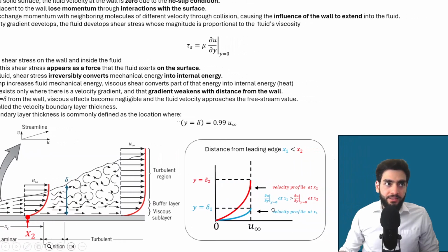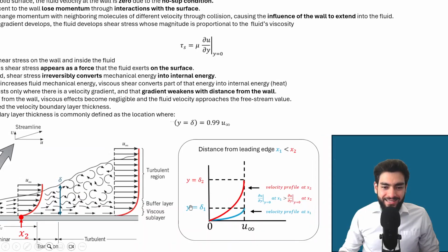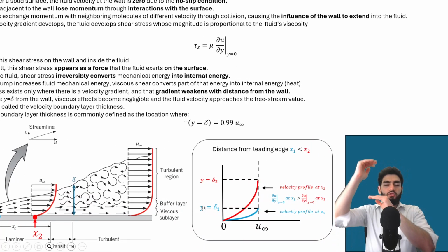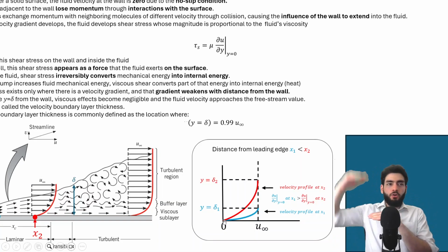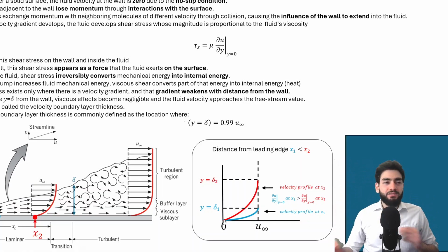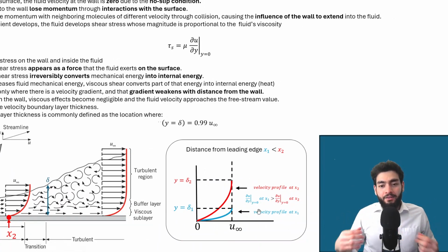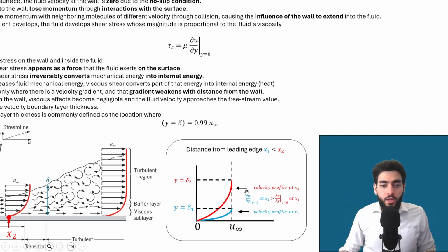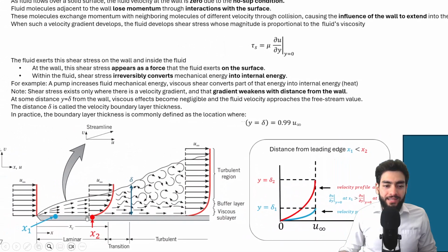And if we look at these graphs, the first boundary layer thickness at the point x1 is a lot smaller, so the velocity change from 0 to the maximum needs to occur in that small distance, and therefore it only makes sense that you'll also have a velocity gradient at the wall, where y equals 0, a lot higher than at point x2.